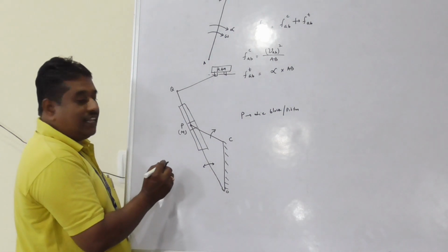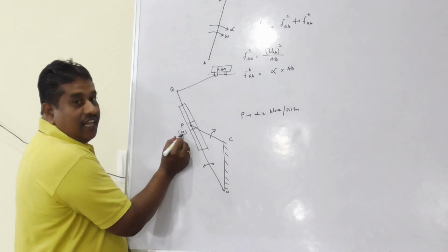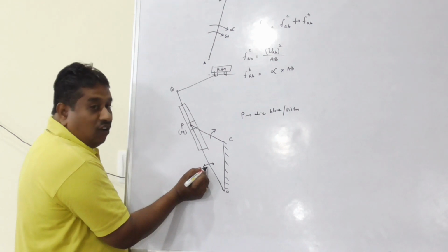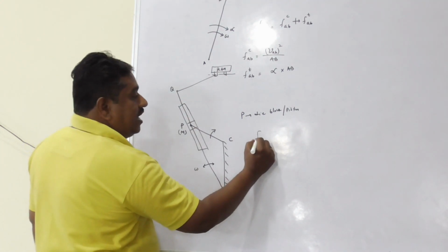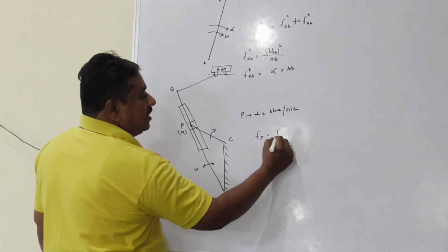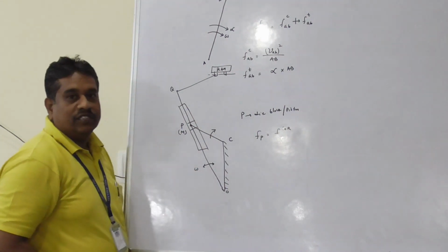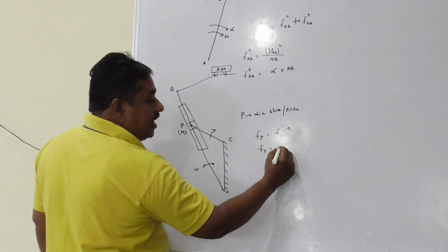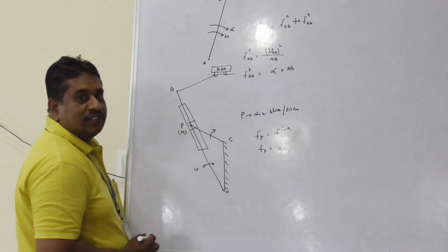At the given instant of time, as the sliding point P coincides with the fixed point M on the oscillating link, when it oscillates with an angular velocity omega, then the sliding point will have an acceleration known as the Coriolis component of acceleration. Along with this, the sliding point will also have a sliding acceleration with respect to M.